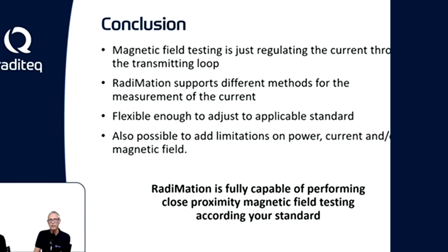And also we are flexible enough to adjust to the applicable standards. It doesn't matter if you have the complete frequency range or only a specific spot frequency that should be tested. Every band can also be a single frequency that's being tested. And also different modulation requirements can be configured, different dwell times can be configured, test levels can be configured themselves. So we are flexible enough to perform this magnetic field test also with different specifications if they are described in different standards.